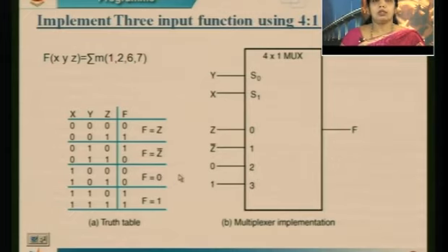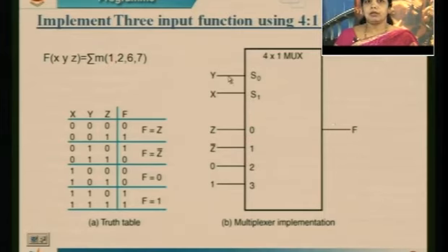It is logic 0. Similarly for 1 1, it is nothing but I3. I will be connecting logic 1 here. So my output function f, whenever I give 0 0, what will be my function output? If I give 0 0 and my Z is 0 or my Z is 1, then my output is redirected here. So my output will be Z.